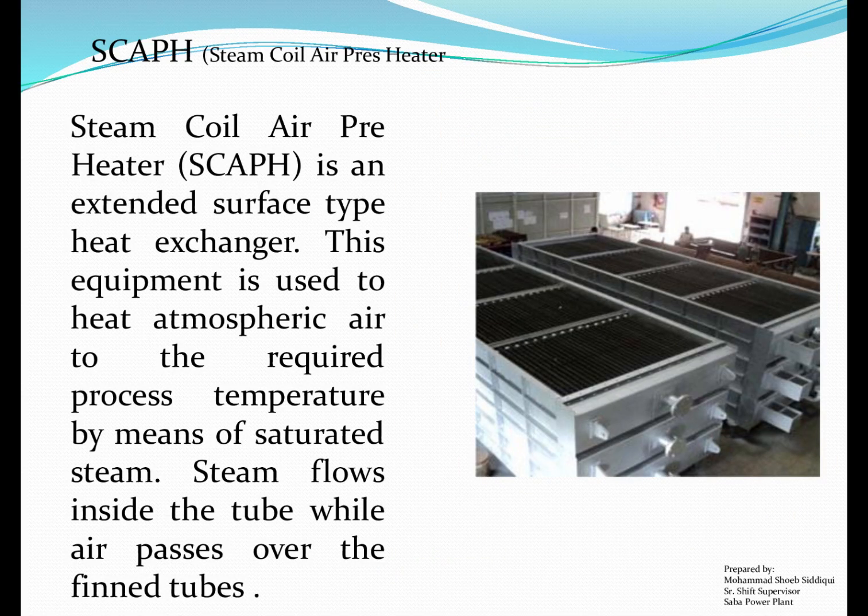SCAPH, Steam Coil Air Preheater. The Steam Coil Air Preheater, SCAPH, is an extended surface type heat exchanger. This equipment is used to heat atmospheric air to the required process temperature by means of saturated steam. Steam flows inside the tube while air passes over the fin tubes.